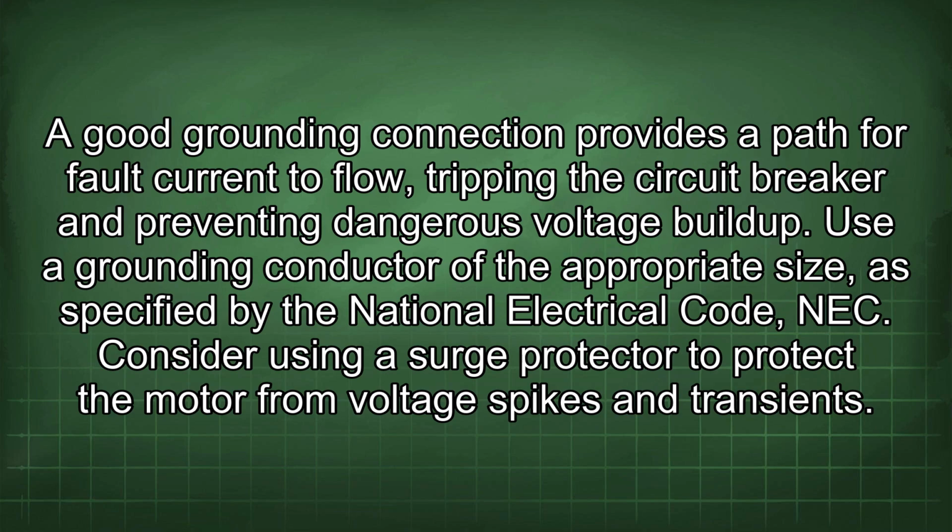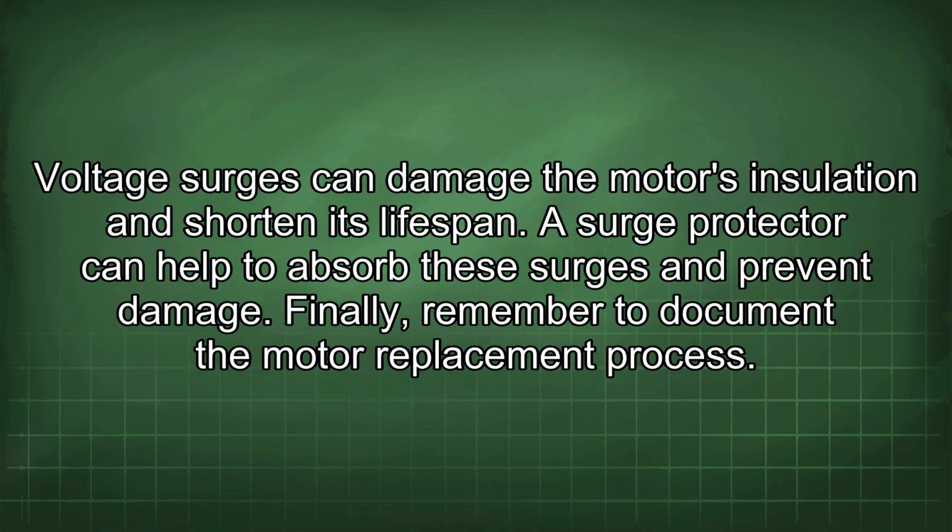Consider using a surge protector to protect the motor from voltage spikes and transients. Voltage surges can damage the motor's insulation and shorten its lifespan. A surge protector can help to absorb these surges and prevent damage.